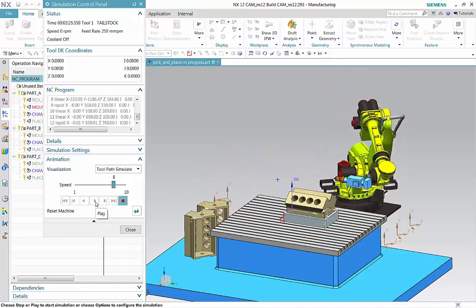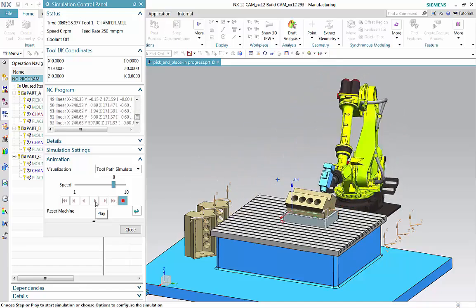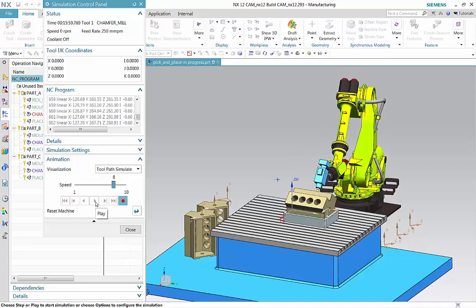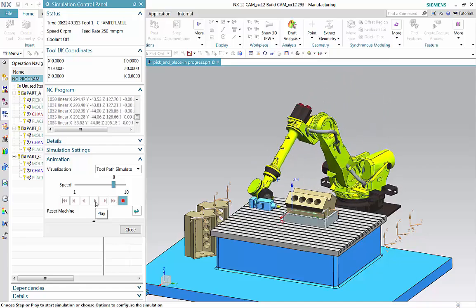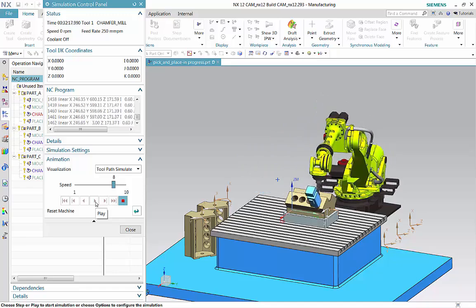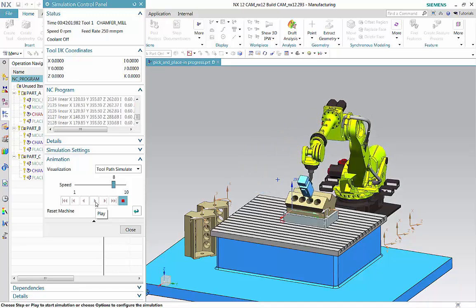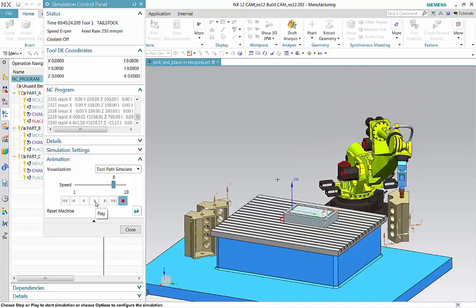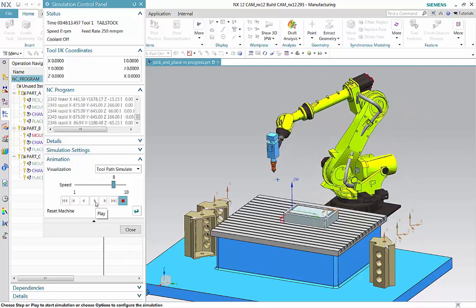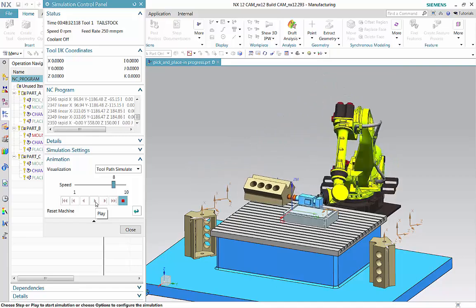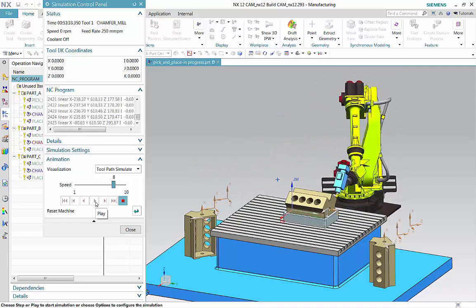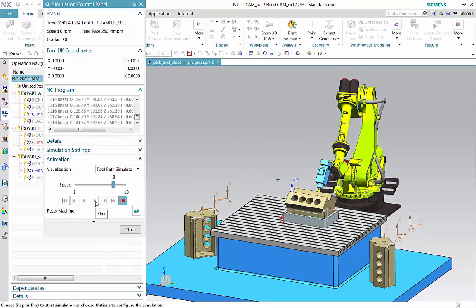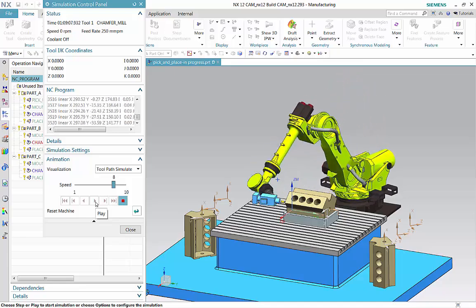You can now create robotic programs to pick and place objects. This enhancement uses existing generic motion capabilities to change tools and palletize parts, and can be used with machining programs to allow you to service the machine tool and perform functions such as polishing, linishing, and deburring. This example will illustrate how you can program the robotic arm to change tools and pick and place parts to perform a deburring operation.